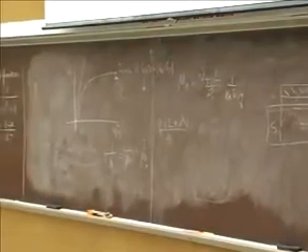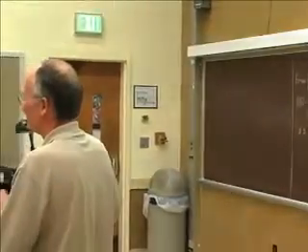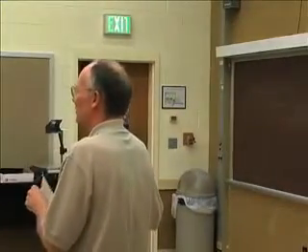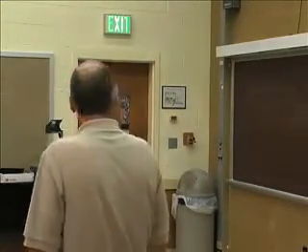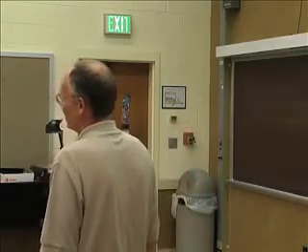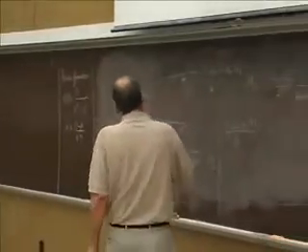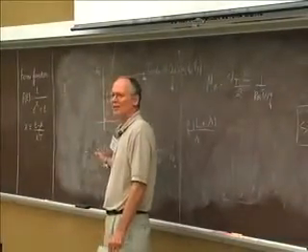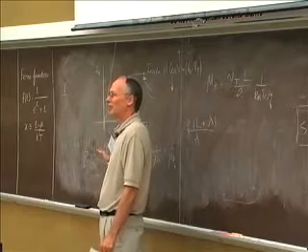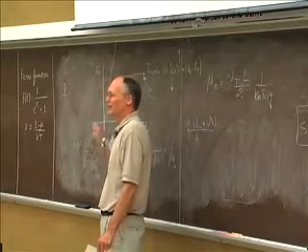Then there are questions. If you get into really small devices, is the effective mass in this very short channel device in that region the same as it is in bulk silicon? To first order, it's pretty good to remarkably small devices. These days, one of the other reasons that III-Vs aren't quite as attractive an alternative as they were initially is that silicon never stays still.